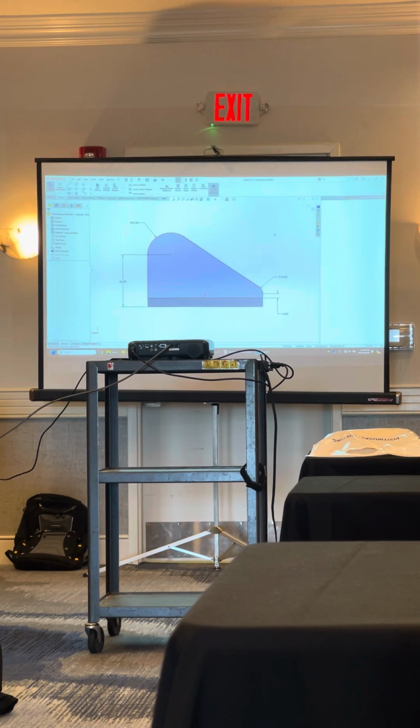The second step is to test the geometry, which then you will start grabbing blue points, not lines, but points, and then grab them and move them. Don't move a little bit, move them around. That's going to show you what's going on. If I have a line that's supposed to be vertical, and I grab a blue point and all of a sudden it's waving in the wind, well then that should direct me to go, oh, this needs to be vertical.